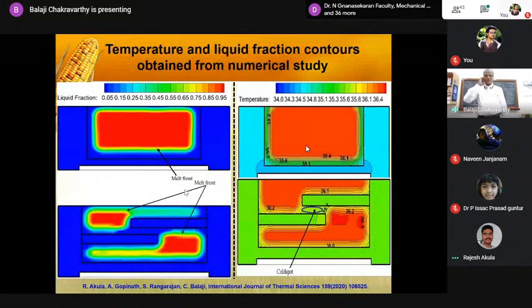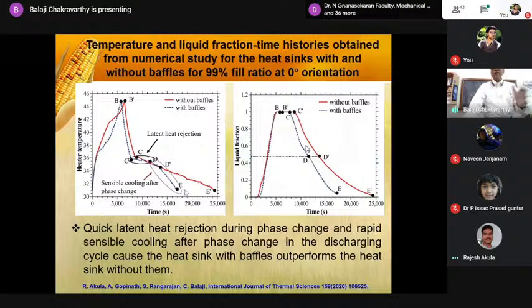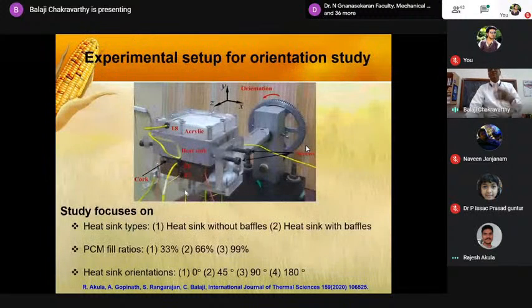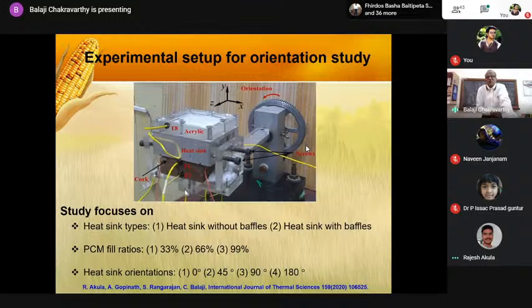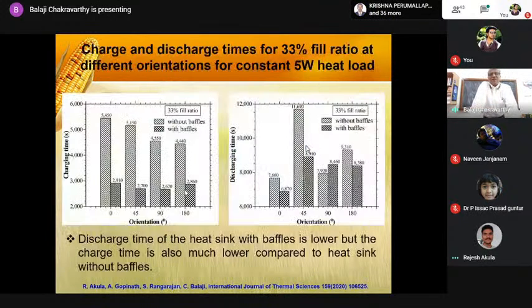Computational fluid dynamics using ANSYS Fluent. So what we do is what is called matchup. What is this matchup? We are assuming adiabatic conditions. The adiabatic conditions won't exist in practice. So what we do is we run the simulations with different heat loss coefficients from the side and the top, and then tune the model such that for one case we get the closest agreement. And whatever heat loss coefficient is there, we use it for running subsequent calculations.